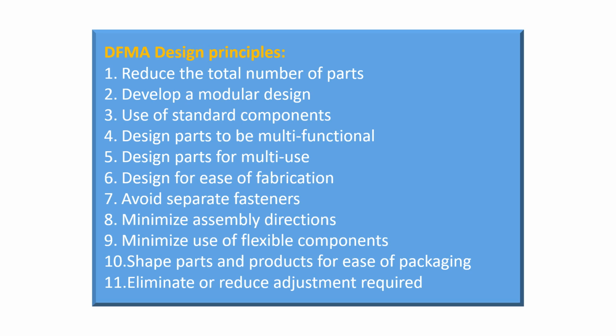10. Shape parts and products to facilitate packaging. The product must be designed in such a way that standard packaging compatible with automatic packaging equipment can be used. Shipping to the customer is easier.